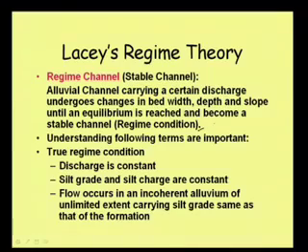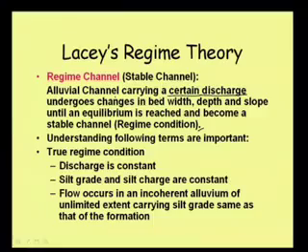As a definition of regime condition, we can state it like this: an alluvial channel carrying a certain discharge. That part is very important, because when we say a channel is in regime condition, we are always talking about it being in regime for a particular discharge. An alluvial channel carrying a certain discharge undergoes changes in bed width, depth and slope.